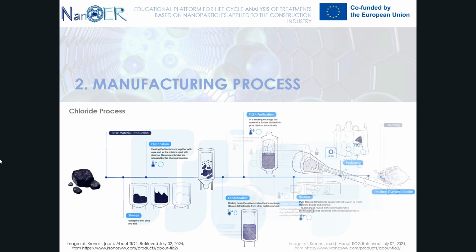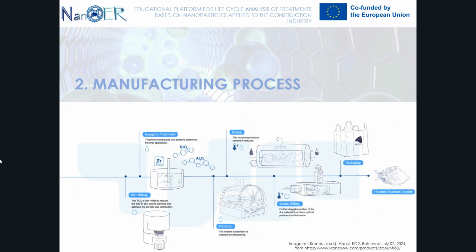The advantage of the chloride process is that the process is short, the production capacity is easy to expand, the degree of continuous automation is high, the energy consumption is relatively low, and the three wastes are few. Also, high-quality products can be obtained. Despite these advantages, it requires significant investment, involves complex equipment structures, and demands high-quality materials.